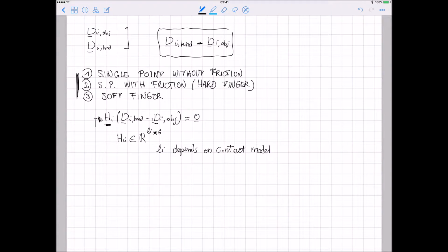So the parallel aspect of the contact, beside the constraint, is the force that we obtain in the contact. So at each contact we can define a wrench lambda tilde i. This is a wrench, so it is composed of a force and a moment.